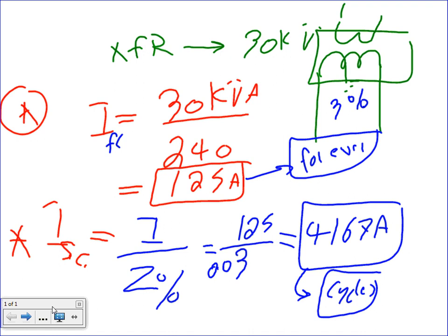Yeah, Brad. Is that on the supply side for us? Is this our circuit breaker, or is it from the utility? The circuit breaker is right here, on our supply side. This is my circuit breaker, right at this point. If you go right here and short these 2 together, grab hot A and hot B and completely short them, this is the amount of current that you expect to get out of this transformer.